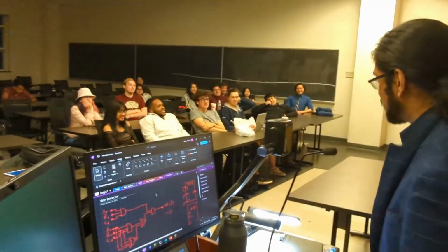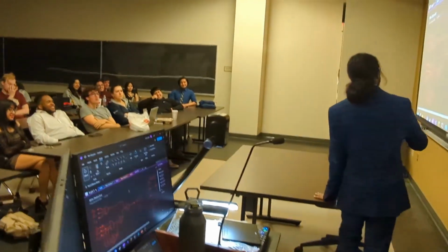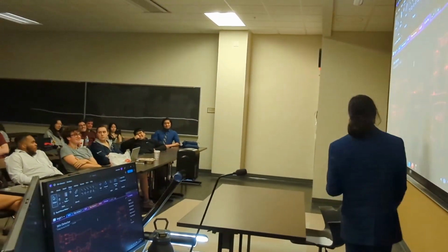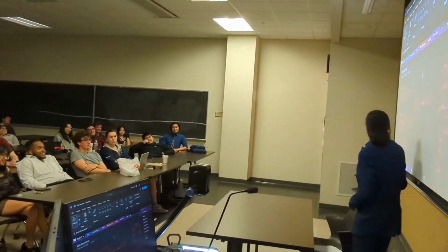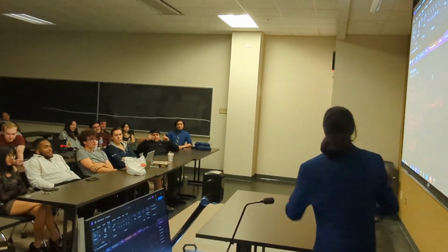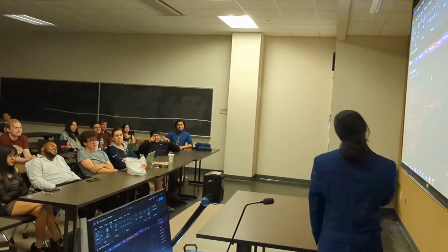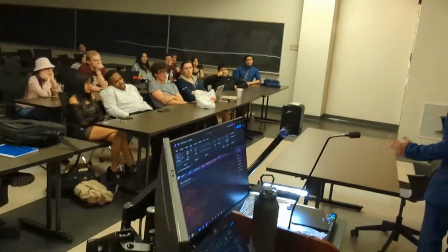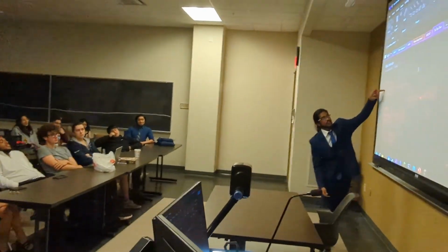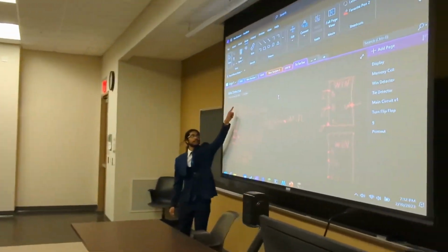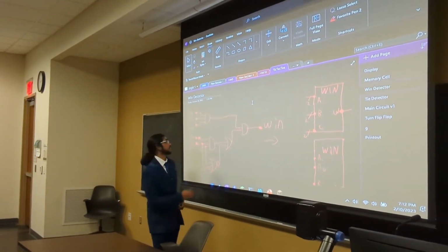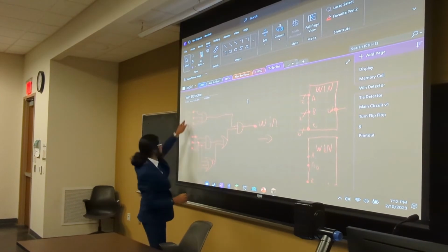All right. So for the win detection, we need to make sure first of all that they have the same value. If we have A, B, and C as our 3 cells, we want to make sure A, B, and C have the same value, but we don't want it to work if everything is blank. That's not what we want. So we need to first make sure that all 3 of the occupied signals are set high, so we send them into a 3-input AND gate and out to this AND gate. So this win detection can only turn on if all 3 of them are occupied.